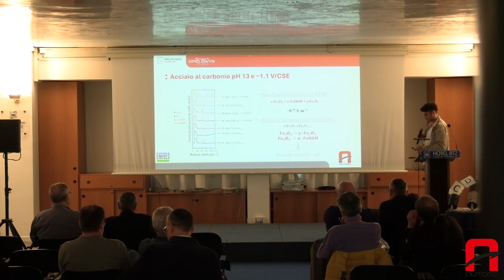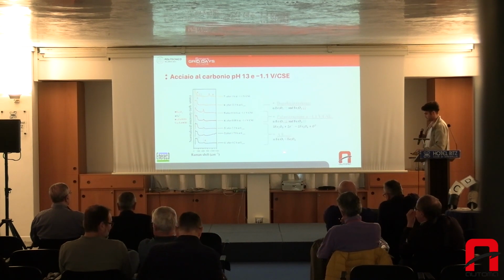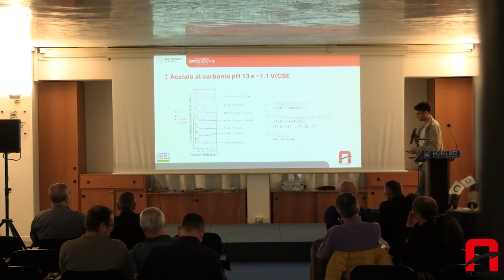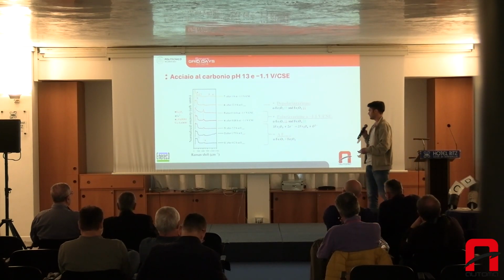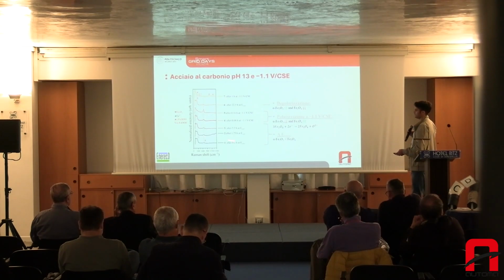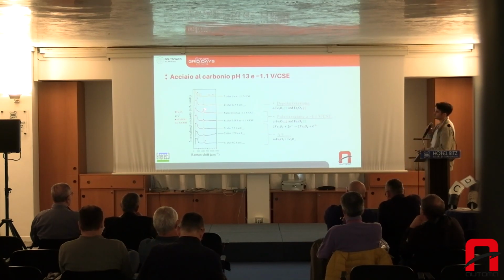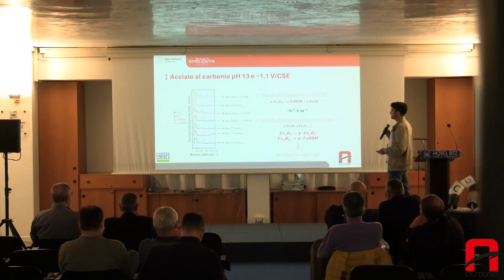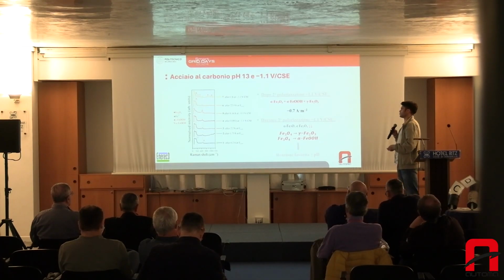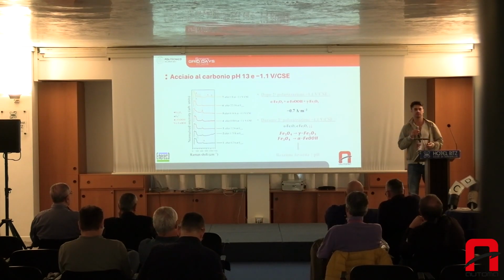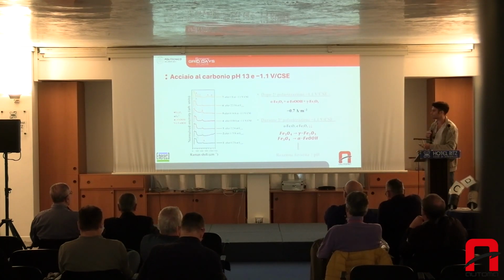These are the stages that get developed on our material in conditions of free corrosion. We mainly have hematite and magnetite. So these are protective oxides. If we do cathodic polarization, the hematite gets reduced, and you only have magnetite, which is less protective. And you see that there is this peak going up. If there are future polarizations, protection currents increase, and this alkalinity has an important effect on the chemistry of the materials being formed.